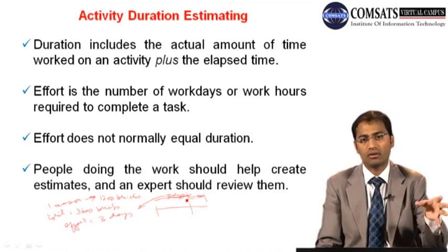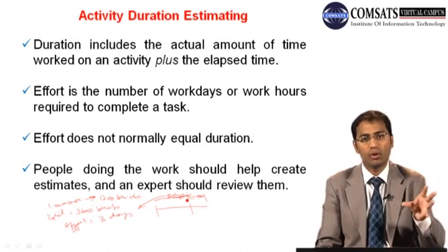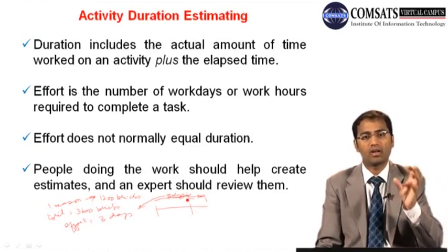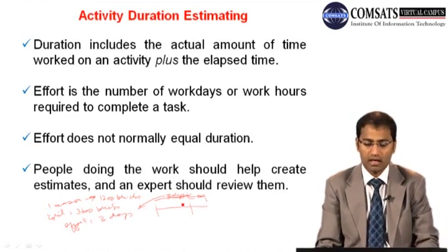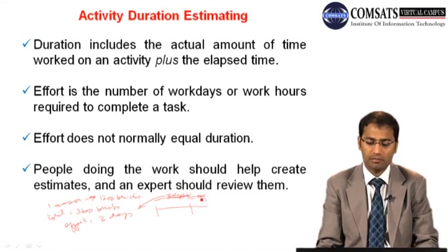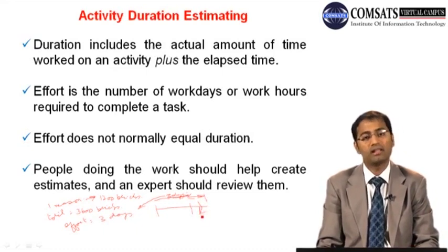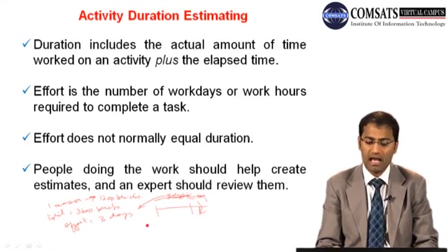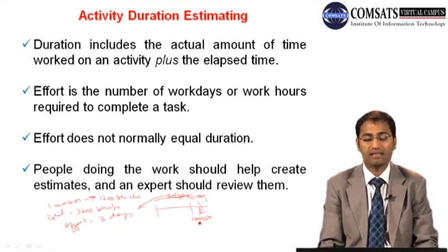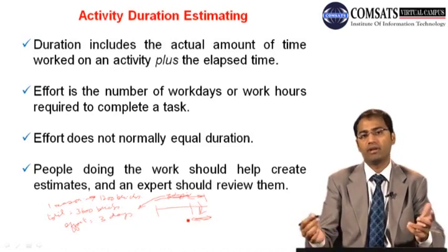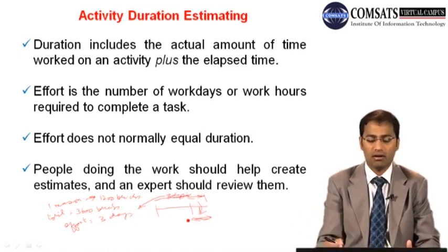You are putting water on that so that it can be cured, and all the cement can get the due strength. So this part is not the effort part. The mason has already gone. And this activity is taking this much as lapse time. You have to leave the completed work for a few days so that you can move ahead.